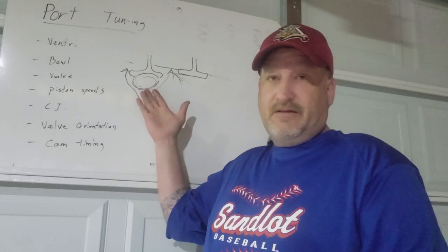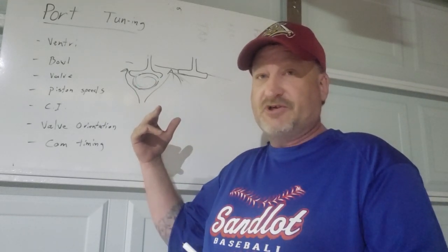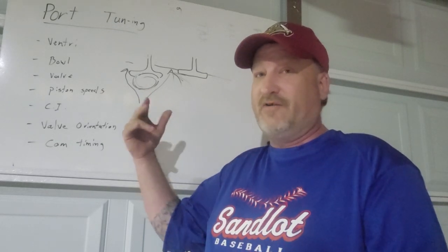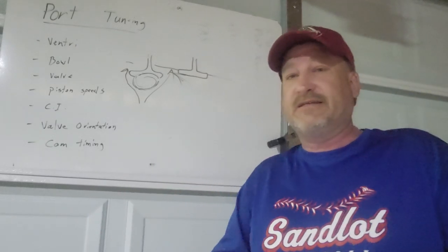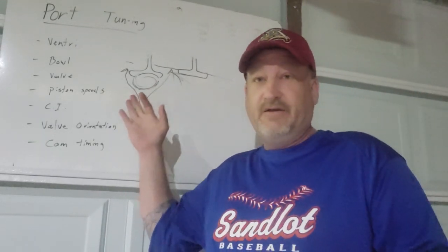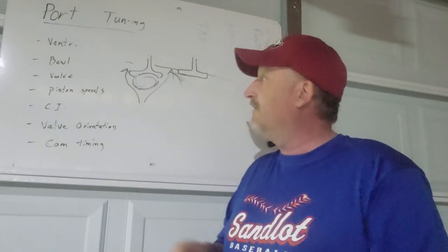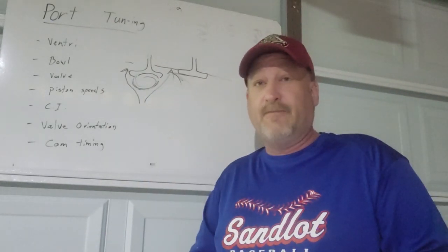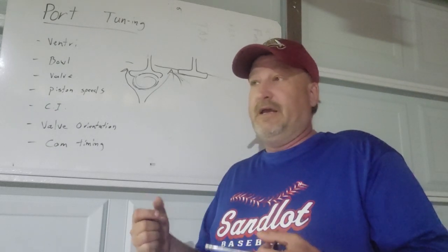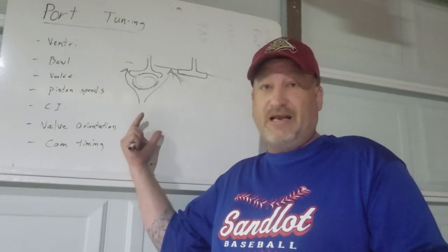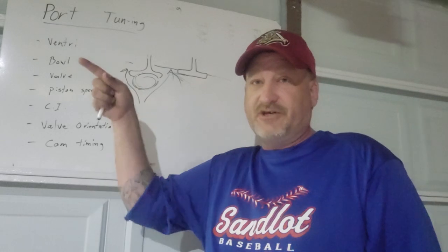So again, this pressure area is going to alter at certain lift numbers and also during different events within the pressure zone of the compressed gases within the cylinder. Port tuning is dictated by the cam timing, the actual design of the valve, and the exhaust port. The faster you can get exhaust gases out and allow that pressure in the cylinder to actually creep up a little bit will help force the exhaust gases in one direction.